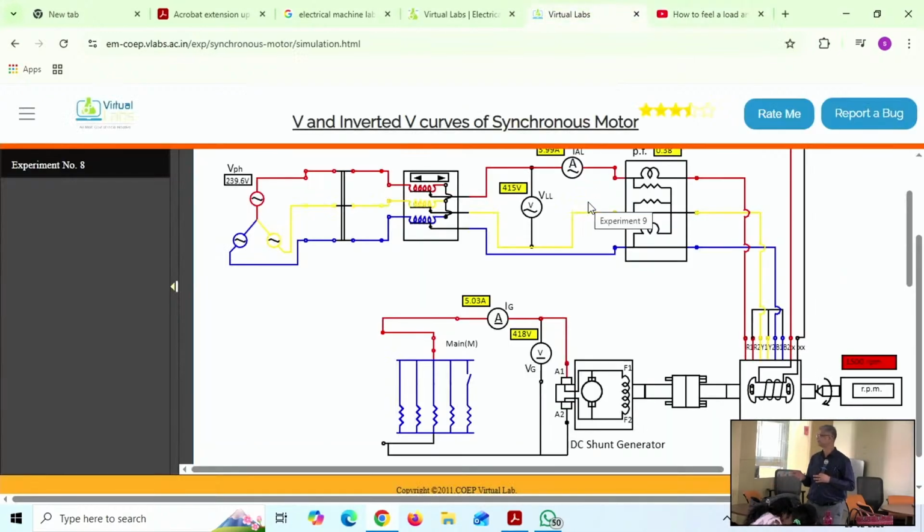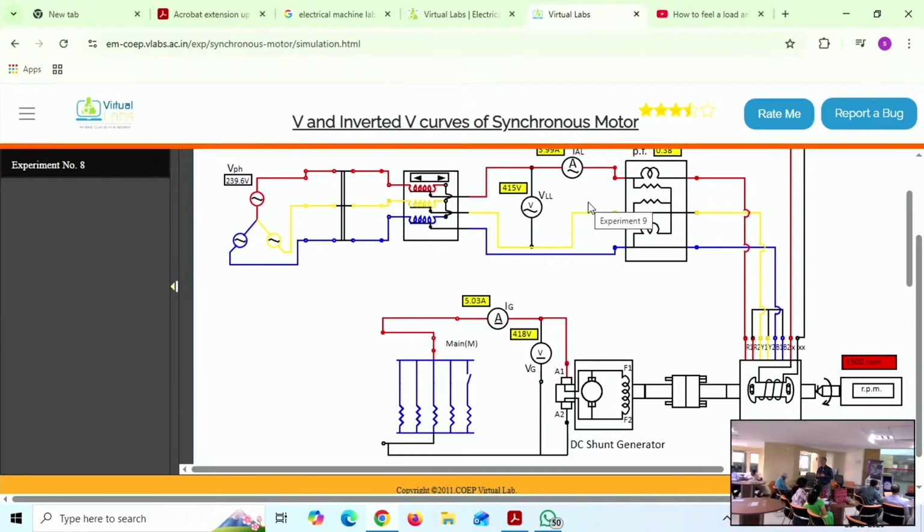But those handling transient stability will see that even if the angle is more than 90, the system is transiently stable. That means if the fault is cleared, how do we make the machines not lose synchronism? It will come back with oscillations, with the equal area criterion. You would have studied this basic concept. It's clear. So don't get confused with torque angle, rotor angle, or the angle between the stator axis and rotor axis. It is the same thing.